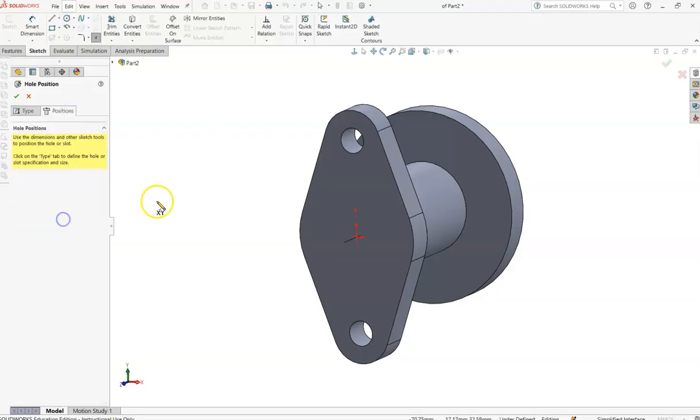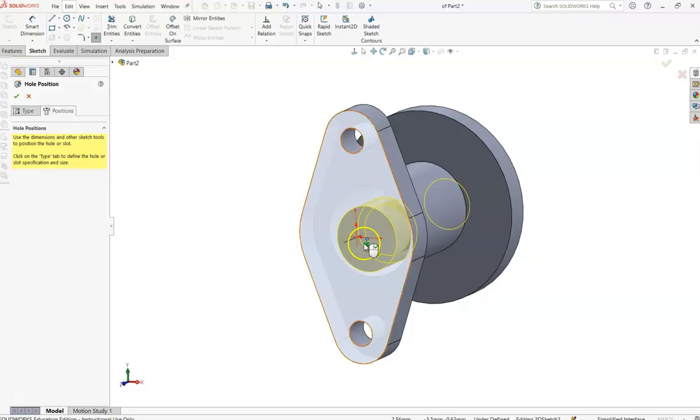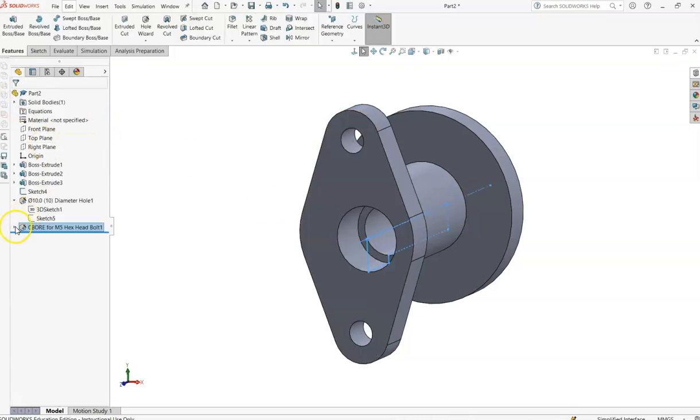Position, 3D sketch. And here's the other one weird thing that I have noticed. When you're trying to put a point on the origin, the 3D sketch doesn't always work. I've tried it with a 2D, and sometimes it also glitches for me. So this is one extra step that you have to do. I just put it to the side a little bit, not too far where it's going to yell at you and say it's not possible, but just to the side a little bit. I hit the green check, and then I go back in and I edit that sketch.